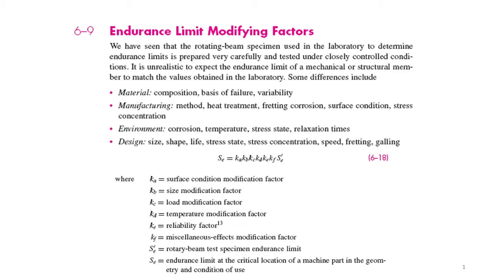Okay. So we know that we need to report the SN curve for a material to be able to calculate the endurance limit, SE, which corresponds to the plateau beyond 10 to the power 6 cycles for steel, and for other alloys such as aluminium alloys that do not have a constant plateau, the endurance limit was agreed to be the fatigue strength that corresponds to 5 × 10^8 cycles.